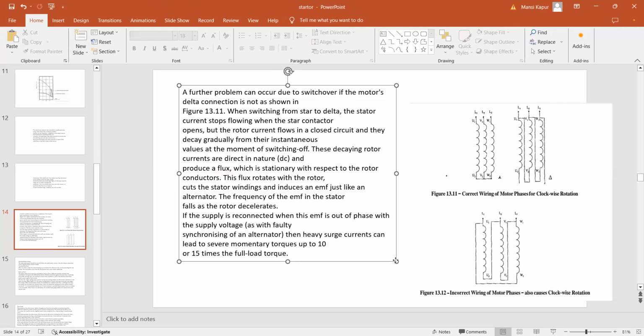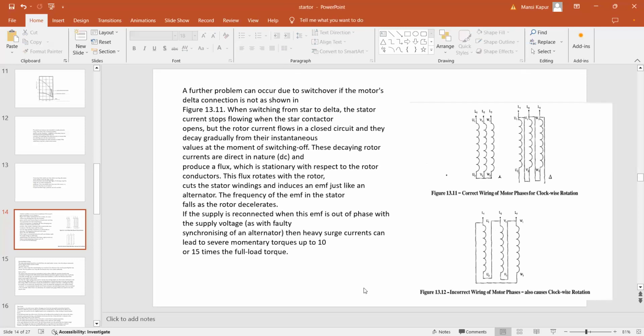So which one is correct and which one is wrong and why? Sir, first, left side topmost number one, A1 is star. Yeah, okay. U1 should be connected to U2 and U2 should be connected to V2.